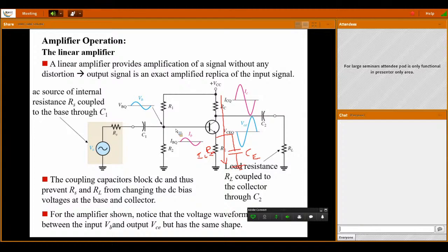So then the total amount of base voltage VB is equal to VBE, the base to emitter junction voltage, plus VE. So if VE is increasing, then the effective base voltage reduces. So here the base current is reducing.